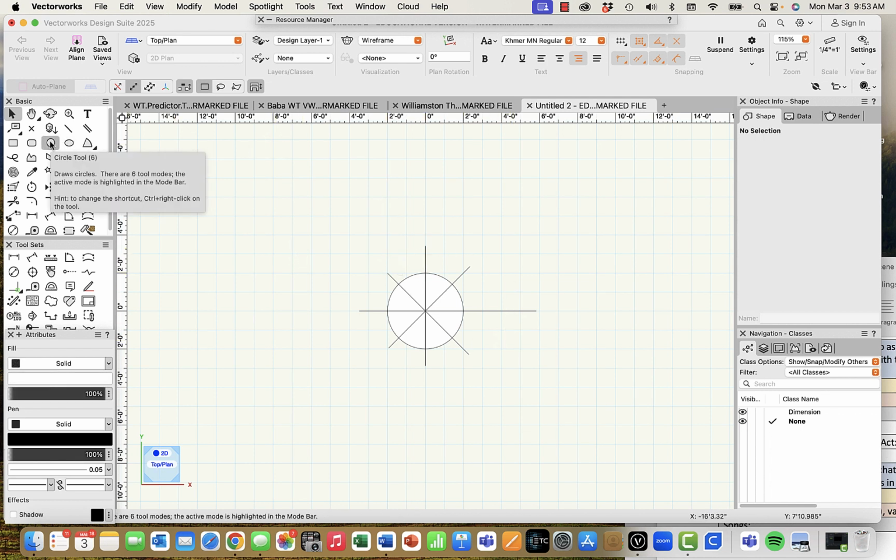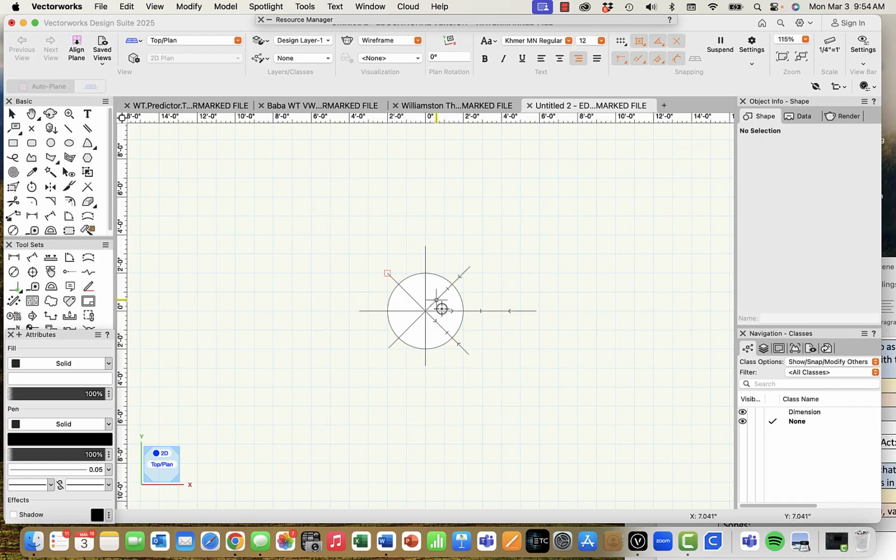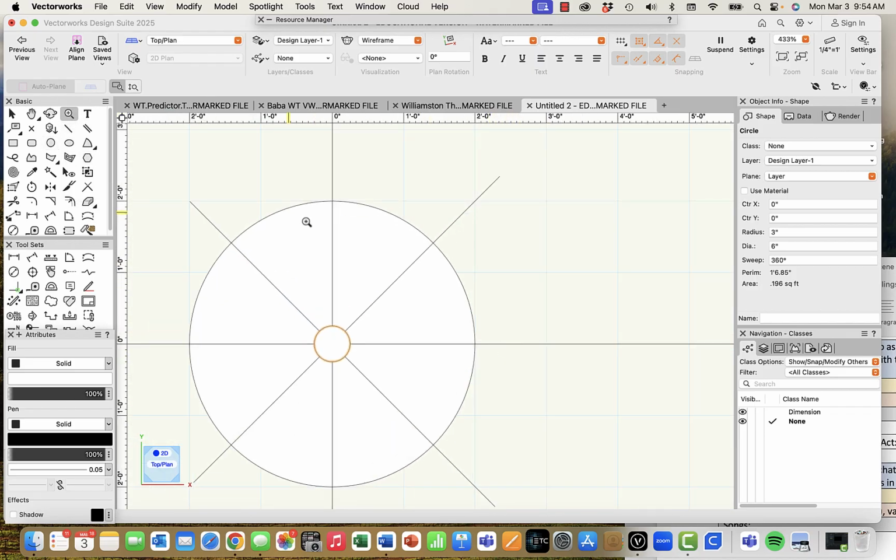Up the center of a spiral staircase, we always have sort of a metal pipe. We want the diameter of that to be 6 inches. And we're going to just place that right there in the center. The next thing we want to do is we're going to just go ahead and draw out one individual stair tread. So the tread is what you step on.